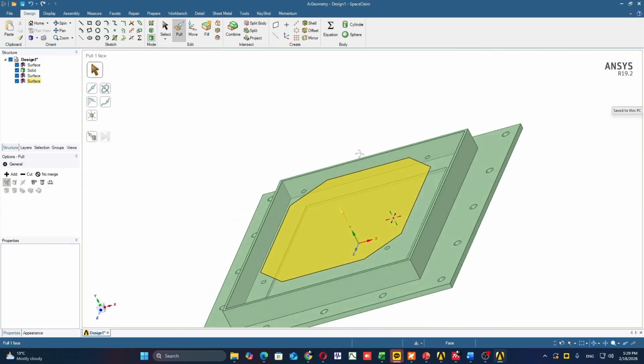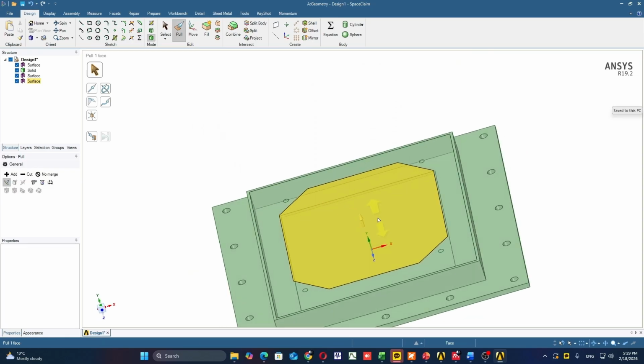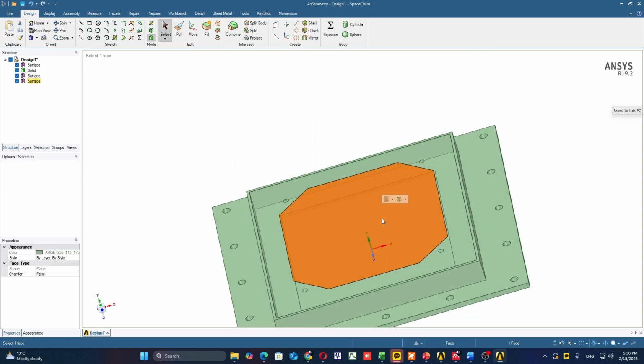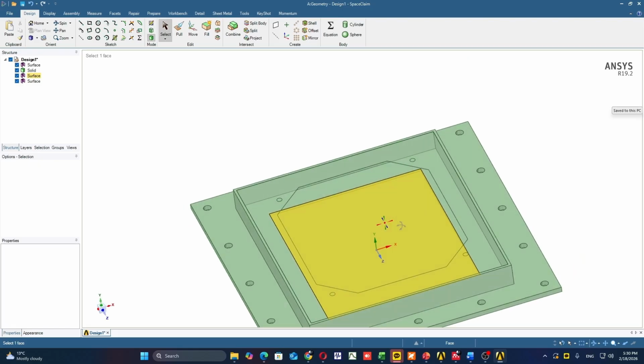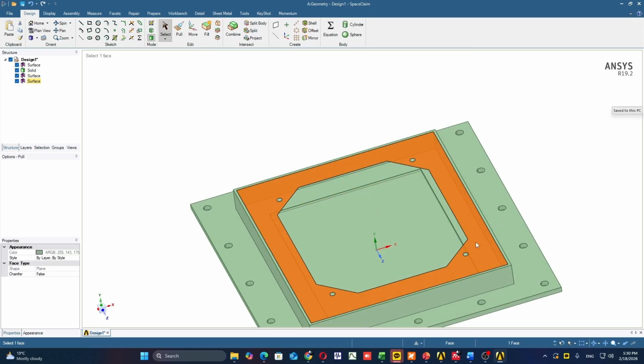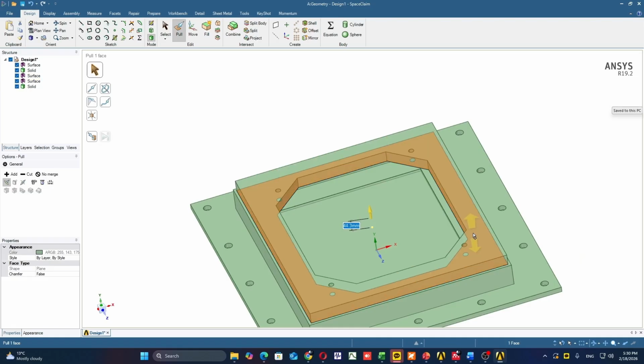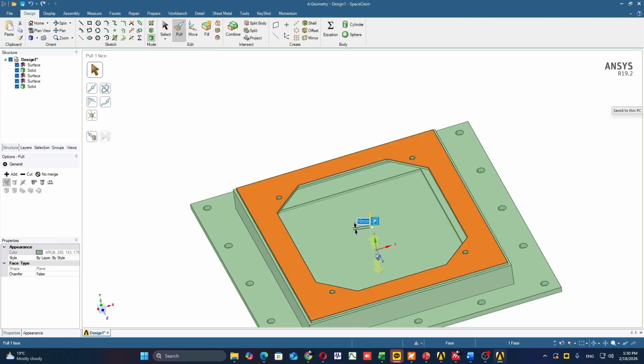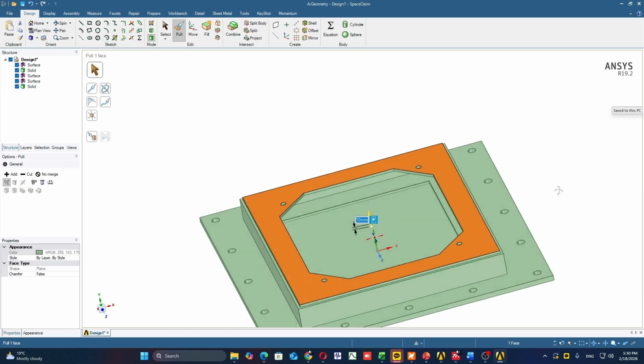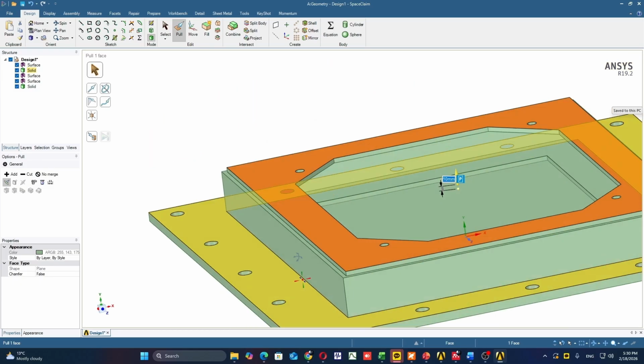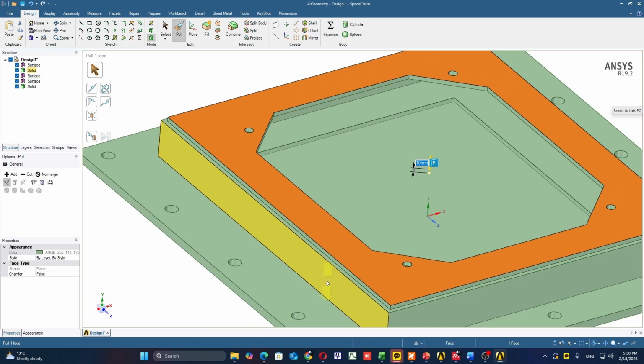Let's go to 3D, and we can delete this surface, we don't need this part. And we can also pull this part to another 10 mm. Yeah, you see a mistake over here, it's only pulling the inside part.